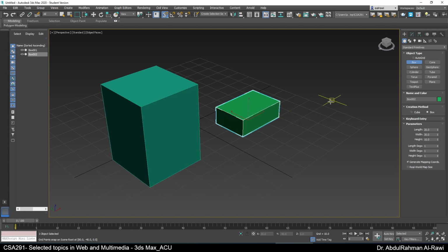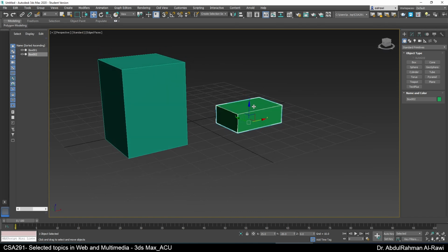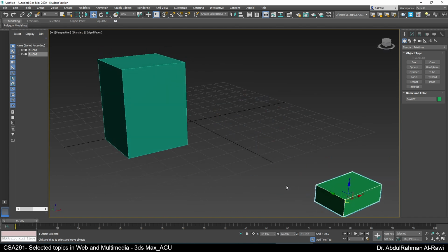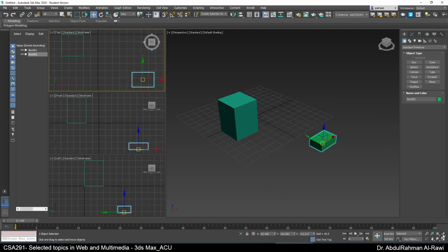Okay, fine. So I will just move this to 2. Oh, no need, actually. Let's just keep them like this. And now let me press S again to deactivate the snap. What if I want to align these objects together? So for example, I just move this somewhere here. I want them just aligned, just like you use even in Microsoft Word. But here it's a little bit more powerful. So to see the align and to see the effect of the align, we need to go to 4 views, and I'm going to just fit them all on screen.